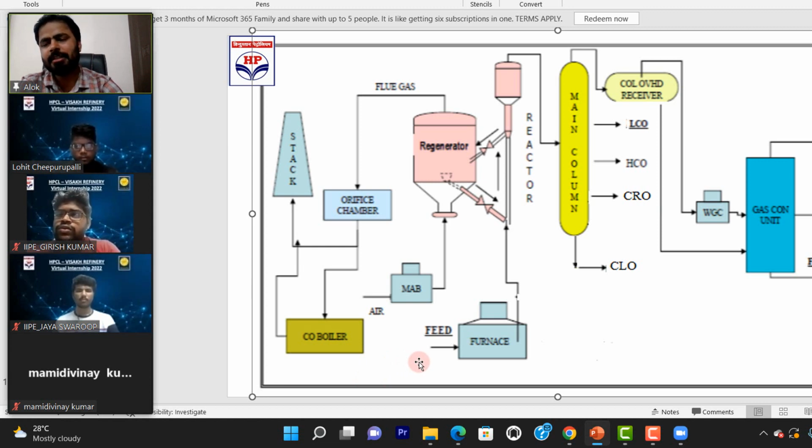Once heated, the feed goes to some 150, 160 degrees Celsius. After that a heater will be there, through which we heat it. We maintain the ROT: we give a set value here, some ROT between 270 to 285 degrees Celsius, say 275 degrees Celsius. After heating, it goes to the reactor. Now I will tell you how we are maintaining the reactor.